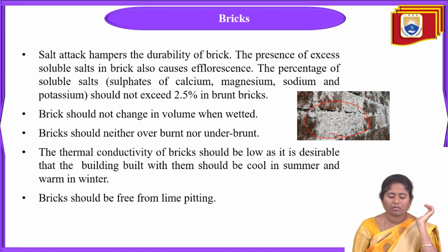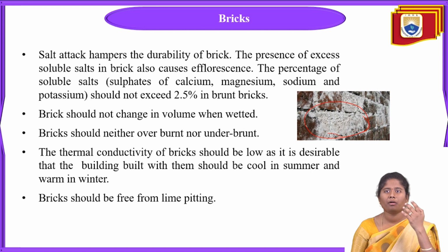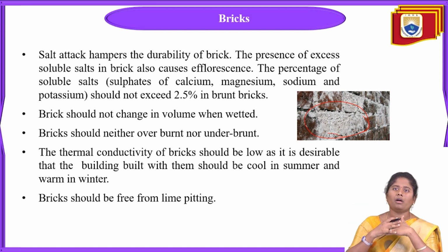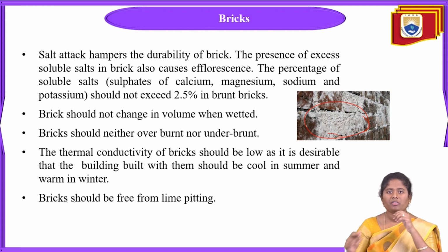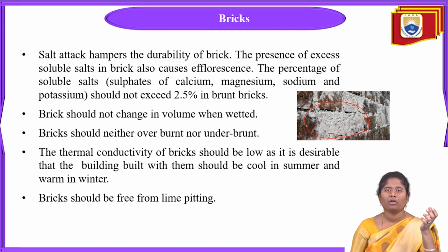If there is salt content in that brick, then when the brick is exposed to the sun and also to ice, snow, and crystal-type ice, a salt layer will form after 24 hours. That's why salt content should not be there in the bricks. Why? Because it will directly hamper the durability of the brick.